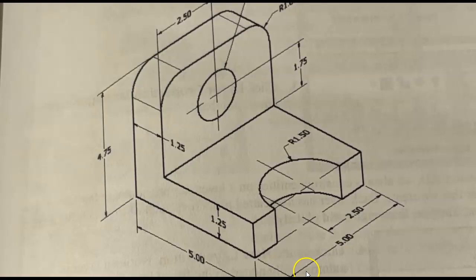So let's go ahead and turn off the snap mode so that we don't have to worry with this. We do want this to be at 90 degrees. We again have to do some math. We know that we're 4 3/4 overall in the height, and the leg thickness here is 1 1/4. So we're going to have to do some basic math. 4 3/4 minus the 1 1/4 will be 3 1/2. So this line length is going to be 3.5.